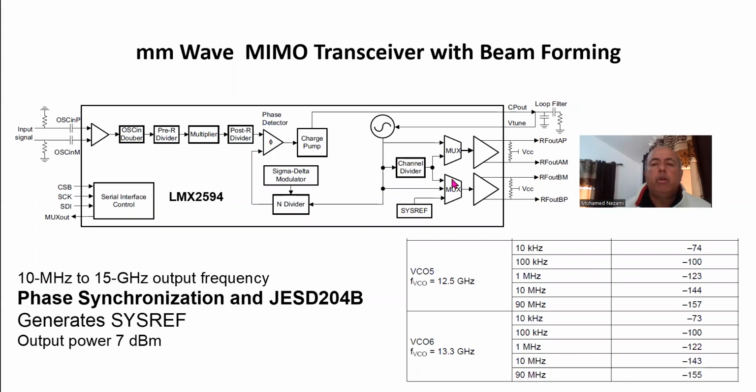So what I'm going to do, I'm going to synthesize an LO that is at half of the frequency. So all I need to do is go up to 14 gigahertz. I don't need to synthesize. It can be just a fixed LO. And so I put in 14 gigahertz, and 14 gigahertz inside the mixer gets doubled up. I've got a subharmonic mixer at X2, which basically synthesizes the up conversion and down conversion at twice the LO. So I feed it half of the LO, and that's why I use this.